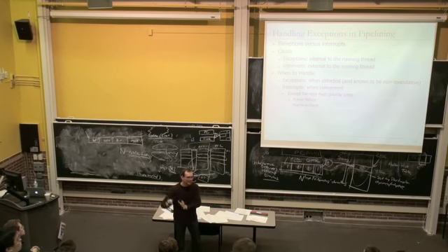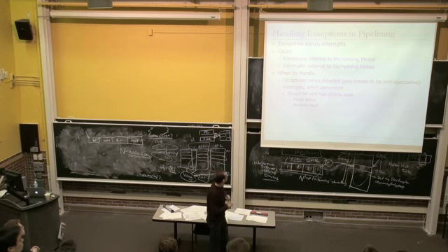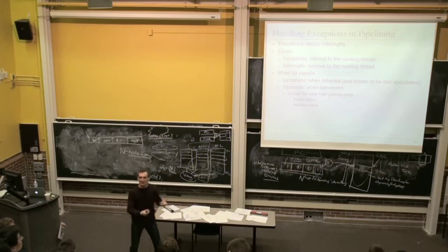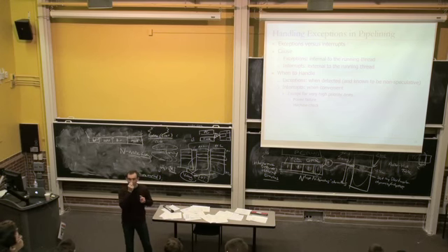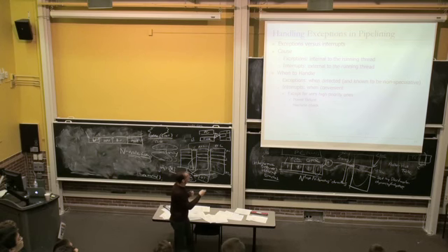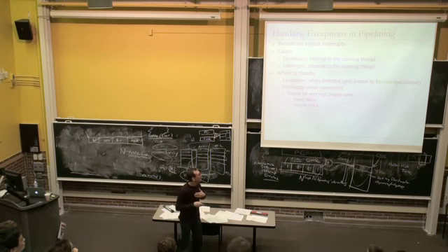Save your state somewhere and prepare for something. Or a machine check interrupt. This usually happens when the hardware detects an error. It raises the machine check interrupt, and that is usually handled at high priority because there's something wrong with your hardware. You may not want to continue executing what you're doing.